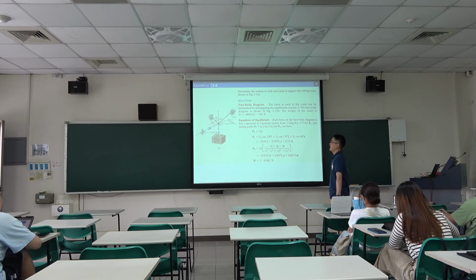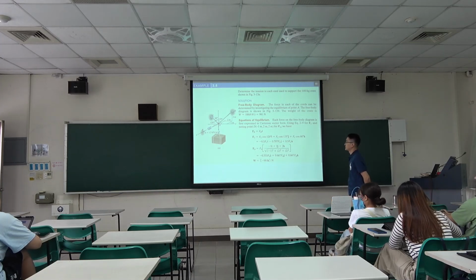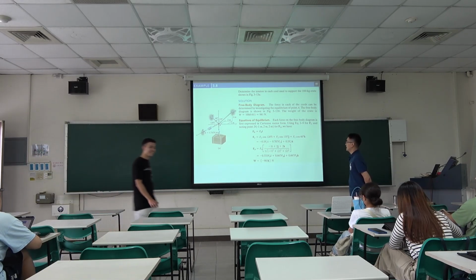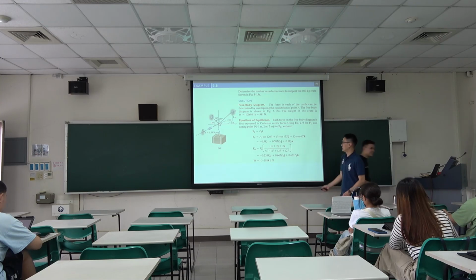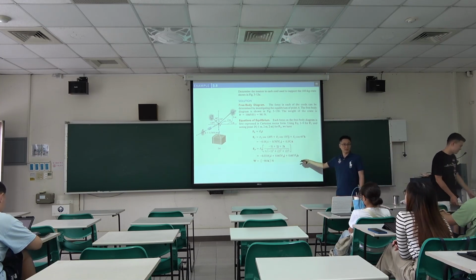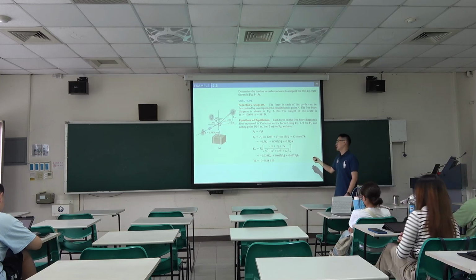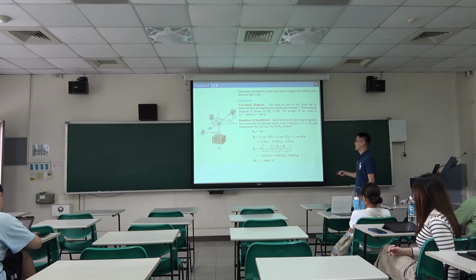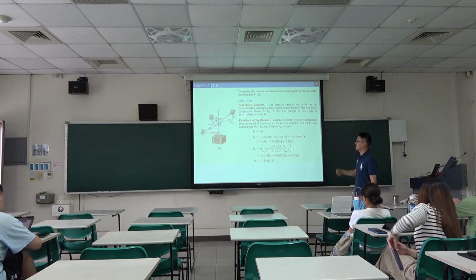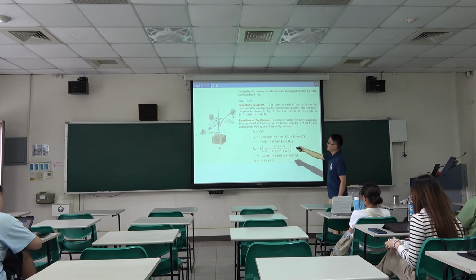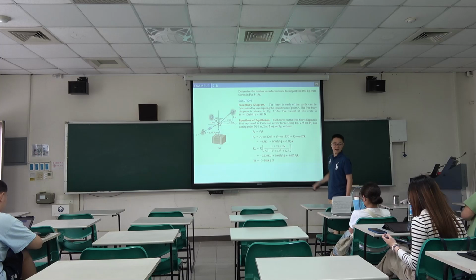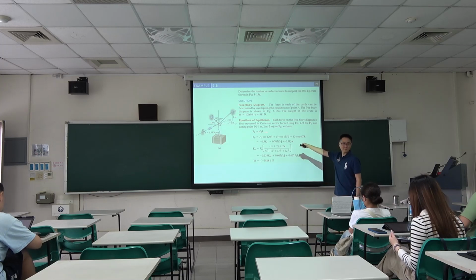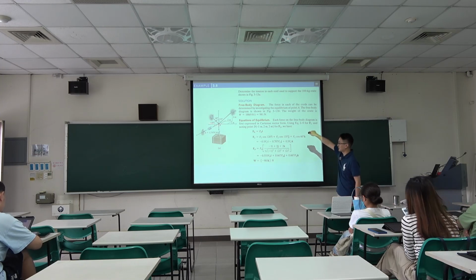And then when we have position vector, we can have a unit vector. Then the summation in each direction equals 0 to obtain the equilibrium equation. Then we can rely on the equilibrium equation to work out FB, FC, and FD. Here FB is along the x-axis, so only one direction of component along the x-axis. Positive is this way.